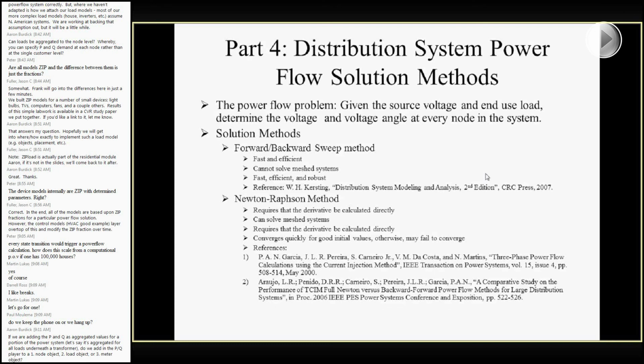And usually the way we'll set that up is we will create a load object that is childed to a meter. And we'll use that meter as a way of doing energy measurements over the course of, say, a month. We want to know how much energy is consumed by that load. The meter objects allow us to do those measurements. So yeah, we can walk through a quick example of that when we get to the end here. But I would definitely say load object is your best bet.